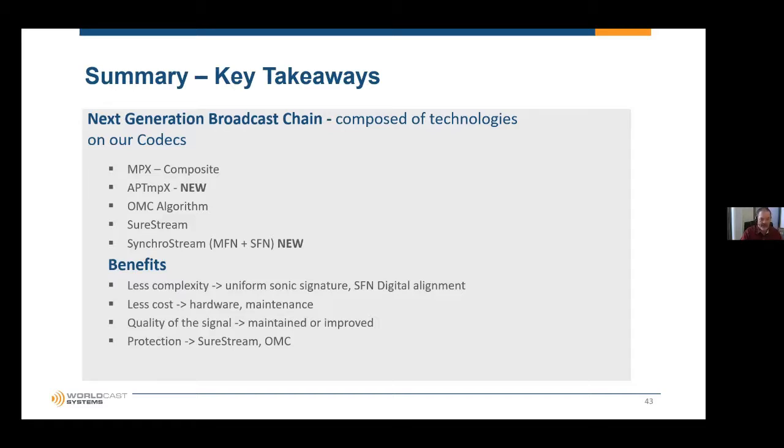The best way is to prevent the packet loss in the first place as much as you can by having multiple streams going across divergent paths, and then to have some sort of algorithm in the decoder end that will detect any overshoots in the composite signal that do come through and take care of them before they get to the transmitter. So you don't have to use that peak limiter for that purpose. So in other words, it glitches if it drops too many packets. If it drops too many packets, yeah. So you protect against the packet loss, and then you have some sort of software in place to mitigate the effects if packet loss does make it through. Gotcha. Okay, thank you. Sure.